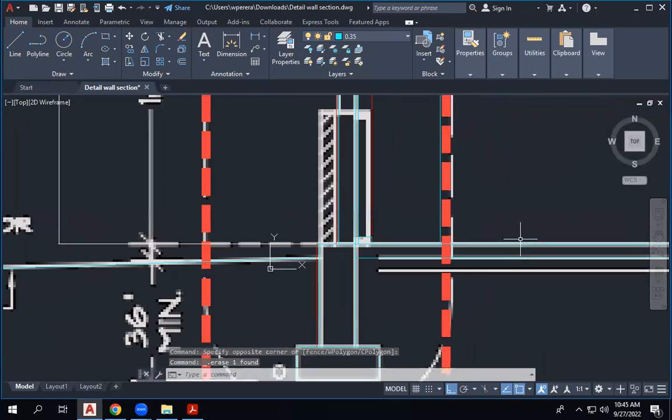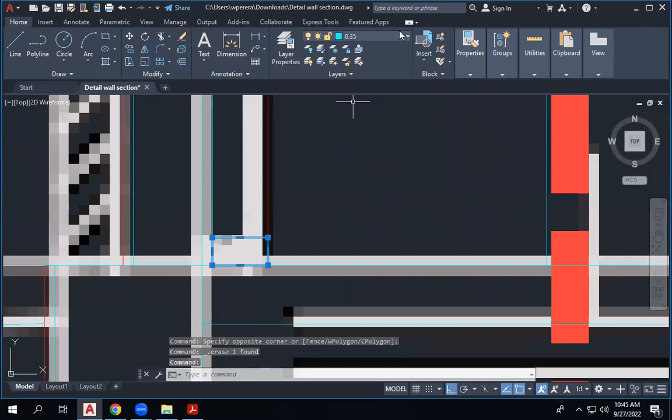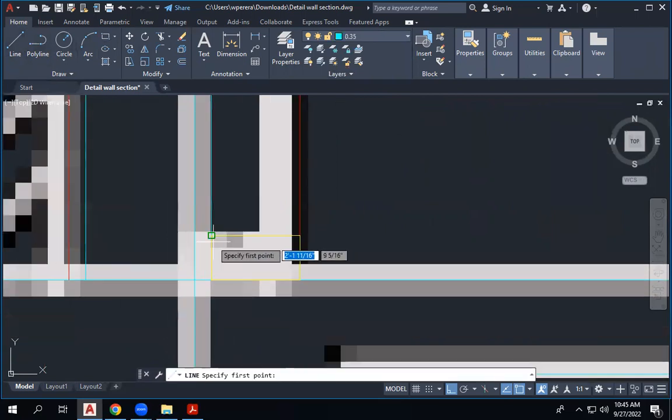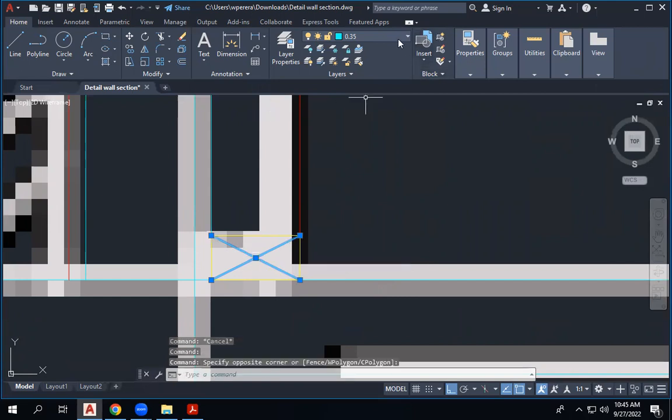So give a different line thickness for that one. As we decided, we will give it as 0.2. And you can have this cross to show that it's a timber section, but we'll give that one the 0 line thickness. Otherwise it will be too dark there. So I'll use this one.